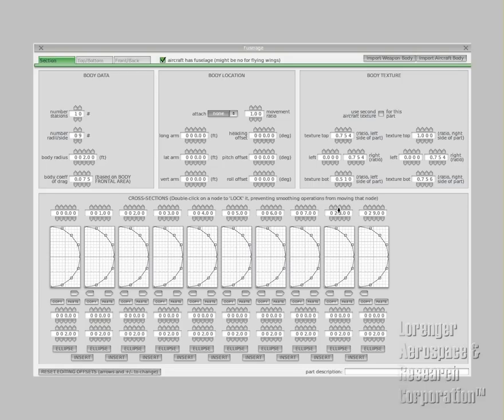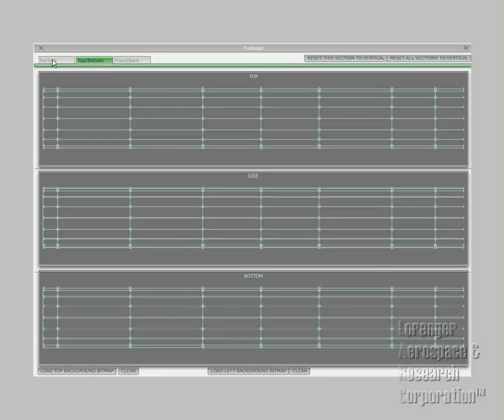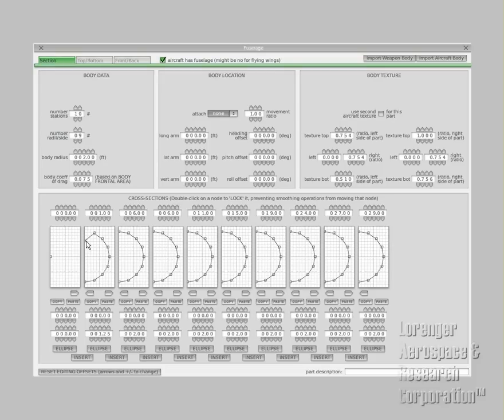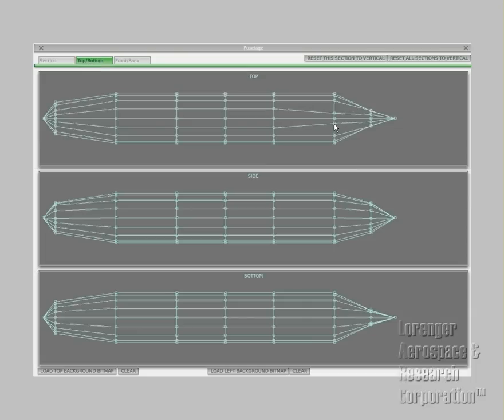Knots, what have you. Next up, I always like to quickly adjust the fuselage to get a general length and rough shape. What this means is you go to these sections here and just trim them out manually. Make rough estimates where you think things will be. You can copy and paste them like so to get the job done quicker. They added that in version 8 of PlaneMaker, I believe. And just quickly slam it together.